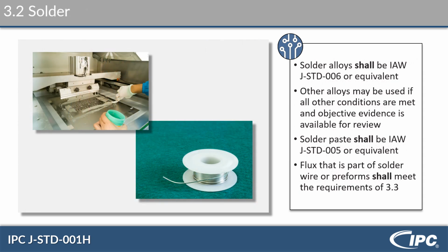I can go back. If you are using a silicone material, it has to be mixed separately with separate tools. You can't mix silicone and non-silicone based items. If you've ever touched silicone, had any kind of silicone on your hands, you would understand why it doesn't always play well with others. It's very slippery, and it can contaminate your bowl, measuring spoon, mixing spoon, or any other material that comes in contact with it.